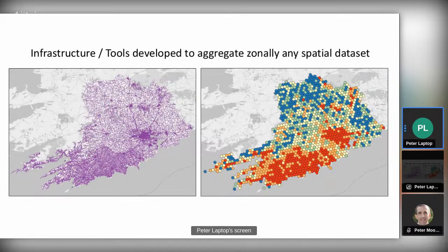When we're talking about, say, extreme flooding events, infrastructure, roads become important. What are the roads that are going to be subject to the most flooding? What are the roads that have perhaps no capacity for flash floods? Where might we need new culverts? Where might we need new drains? Which are the roads that are going to be subject to the most change over time?